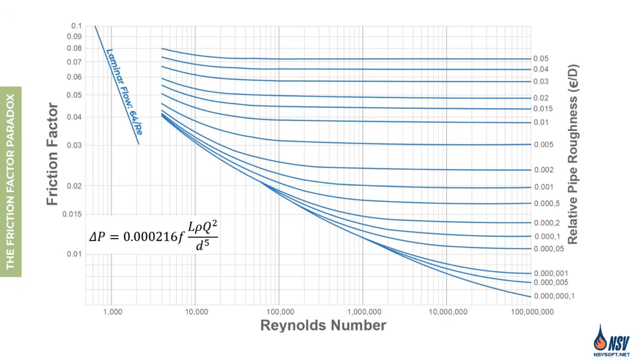When we examine the Darcy-Weisbach equation, two opposing effects appear as flow increases. On one hand, increasing the flow rate causes the friction factor to decrease slightly. On the other hand, the pressure loss term is proportional to the square of the flow rate, and this relationship dominates the behavior of the equation. In practice, the modest reduction in friction factor is overwhelmed by the much larger quadratic growth of the flow term, and it's not a fair fight. The flow squared term always wins.